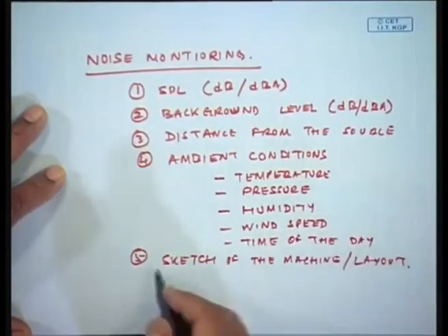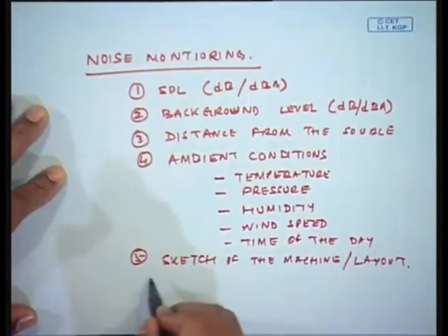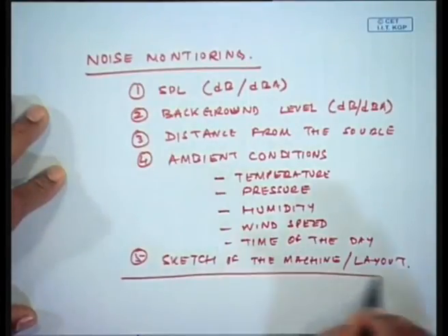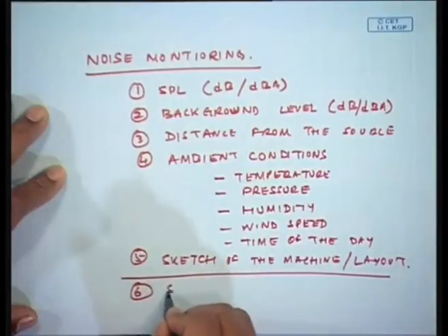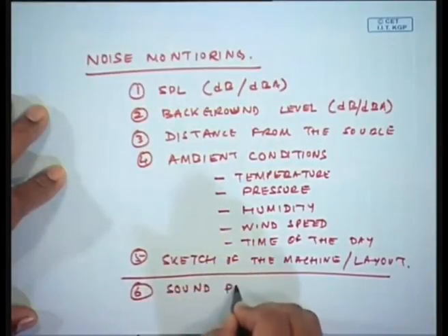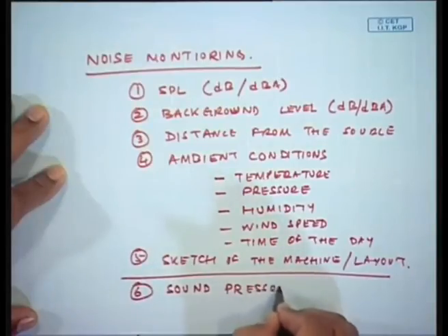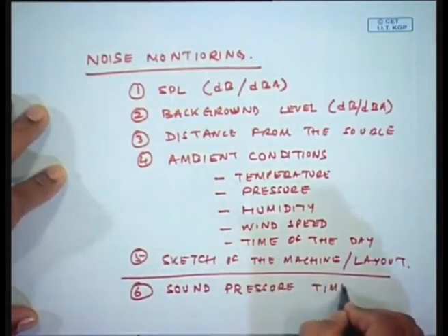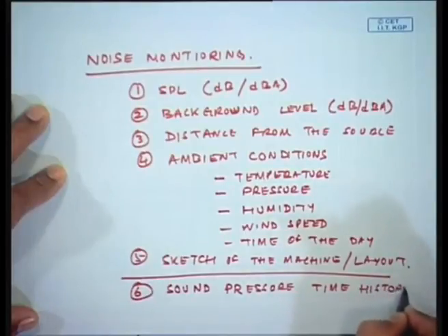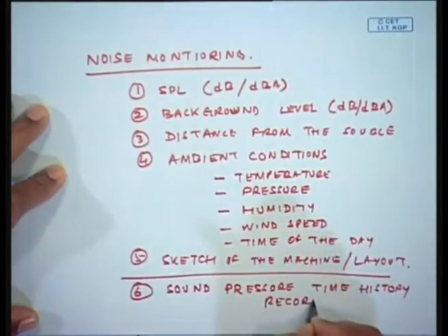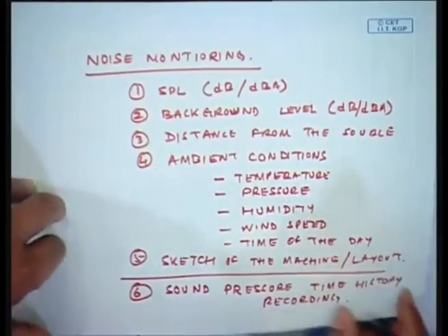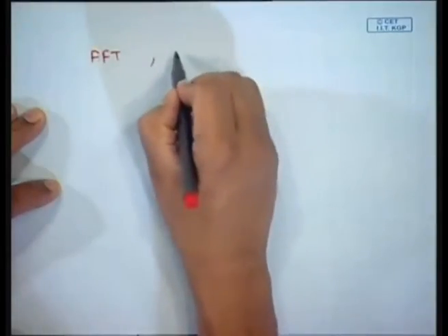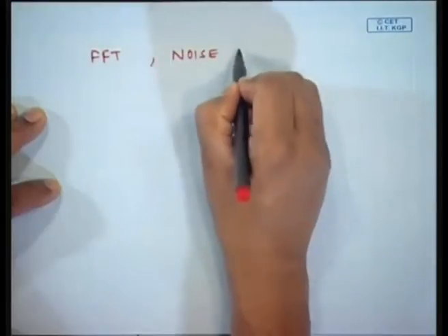And later on for diagnosis, sometimes we may do a sound pressure time history recording and store it with us. For example, we can still apply the techniques of FFT to get what is known as the noise spectrum.